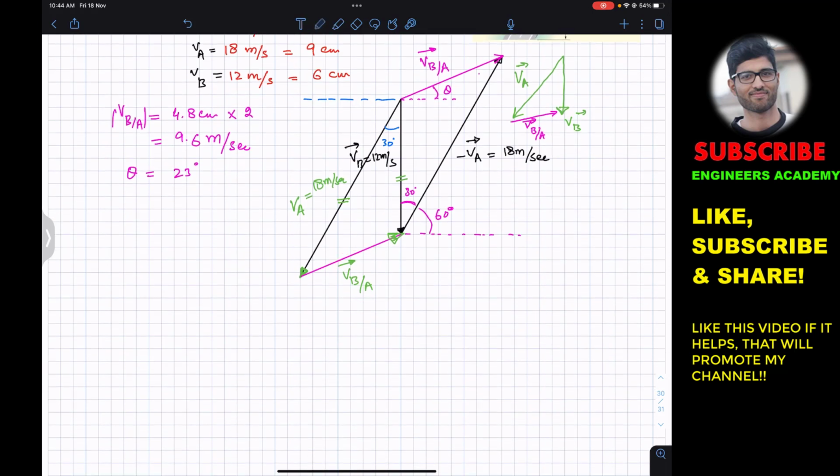So now if I apply the cosines law, we can say that VBA magnitude square is equal to VA square plus VB square minus 2 into VA VB cos of the included angle between VA and VB.